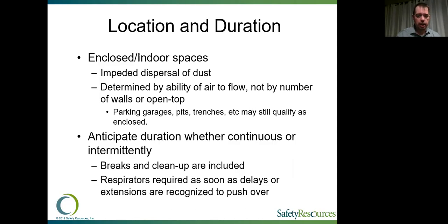So things like parking garages, pits, and trenches, even though they may seem like they're somewhat open and may not technically be an enclosed space, you really have to look at the airflow to make that determination of whether or not you're going to be able to qualify it as enclosed or outdoor spacing. And then again, when we look at those duration requirements, we really need to anticipate what that duration is going to be, whether it's continuous or it's being performed intermittently.